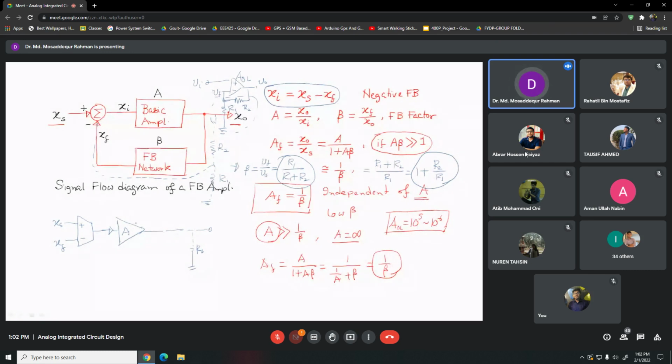But amplifiers are designed to handle low power, not large power or large current, while the load will demand large power and large current. Different loads will demand different amounts of power and current, so it depends on the load, but we don't know in advance. So in order to provide large current to the load, we add another stage at the output. So we have an output stage.